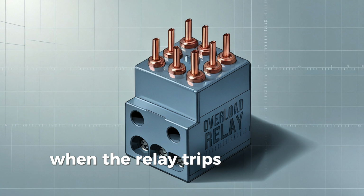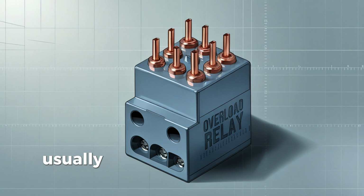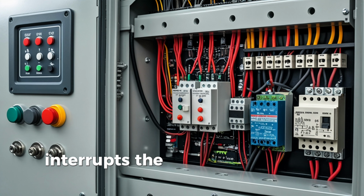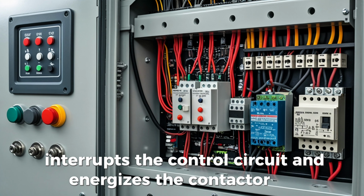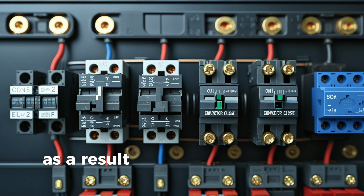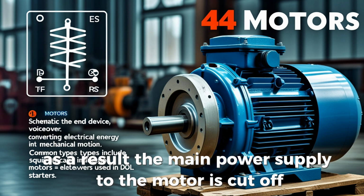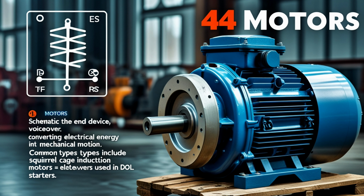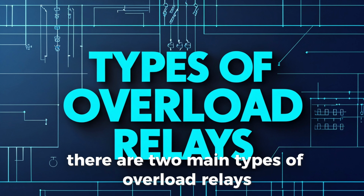When the relay trips, it activates its internal contacts, usually a normally closed contact in the control circuit, which in turn interrupts the control circuit and de-energizes the contactor coil. As a result, the main power supply to the motor is cut off, stopping the motor before it can overheat and sustain damage. There are two main types of overload relays.